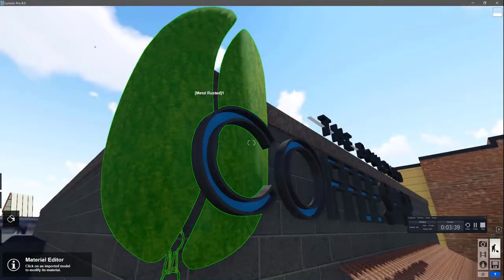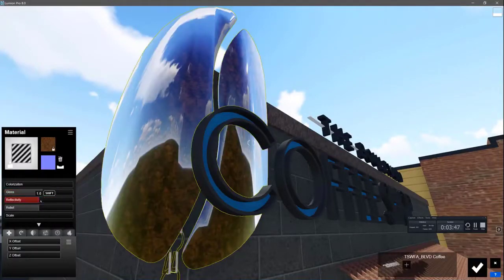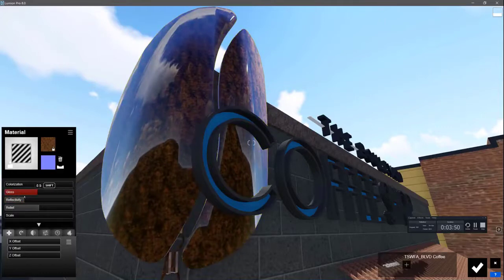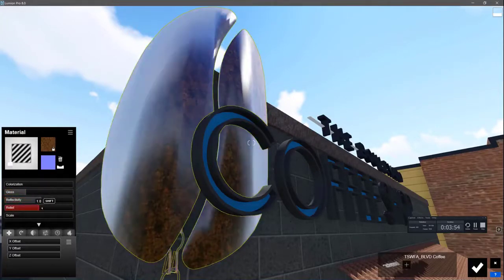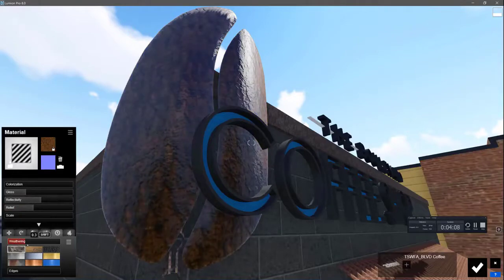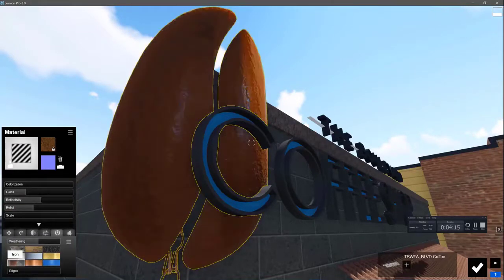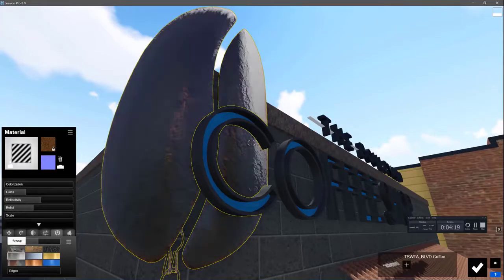If you're good with texturing in your modeling program, it is best to add Lumion properties to the imported materials. Make it a standard material and adjust the gloss, reflectivity, and relief. There are several other tabs to adjust position, orientation, transparency, settings, weathering, and foliage. With these sliders, it's easy to achieve an authentic look.